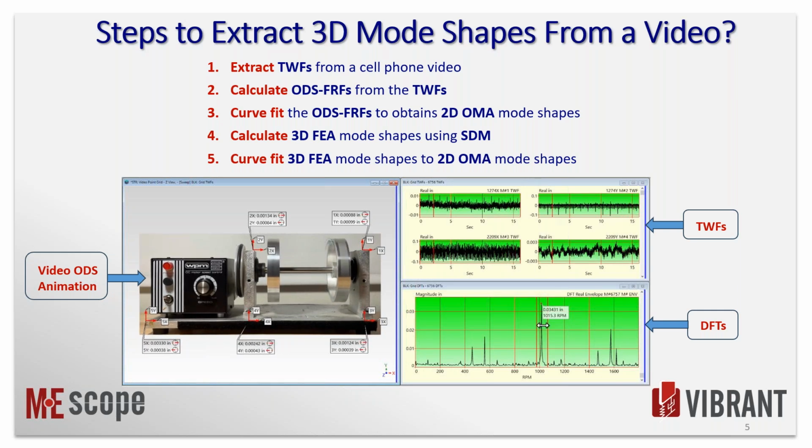Let's see, the same gentleman, Robson, says, I've tried using high-speed cameras from another vendor before, but we were unable to capture the mode shapes for frequencies above 5 kilohertz, which is critical for my application. Yeah, now when you get up to 5 kilohertz, you've got to use floodlighting because the optical sensors in the camera just don't pick up enough light. So that is a disadvantage of going to 5 kilohertz sample rate with a high-speed camera. You've got to set up the lights and make sure you don't have flicker in the video and so forth.